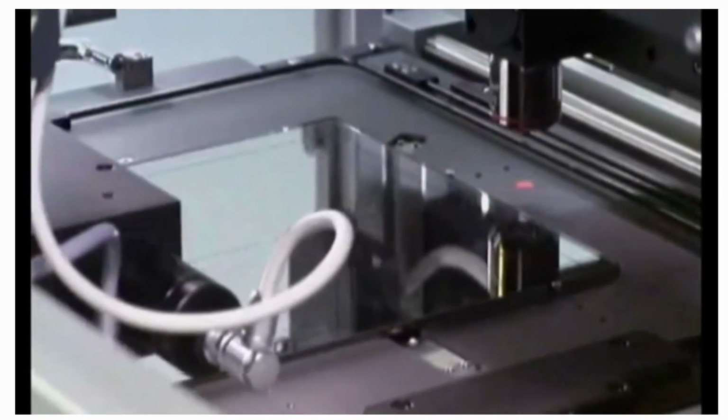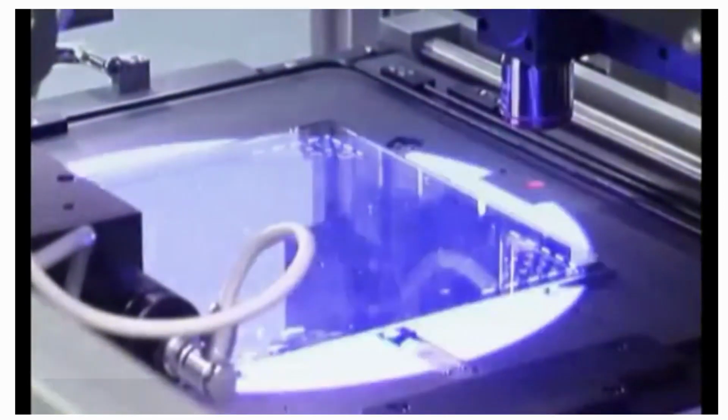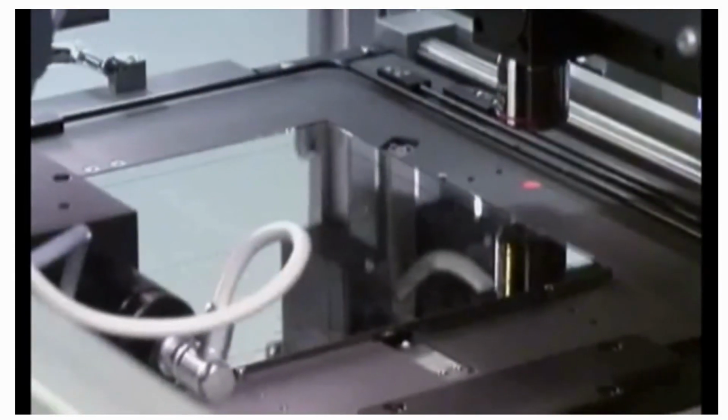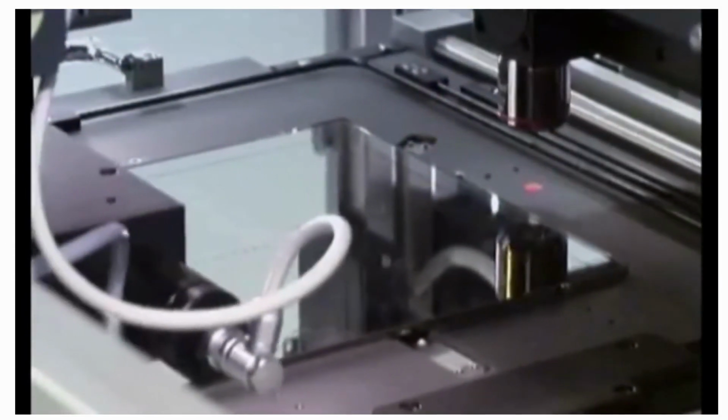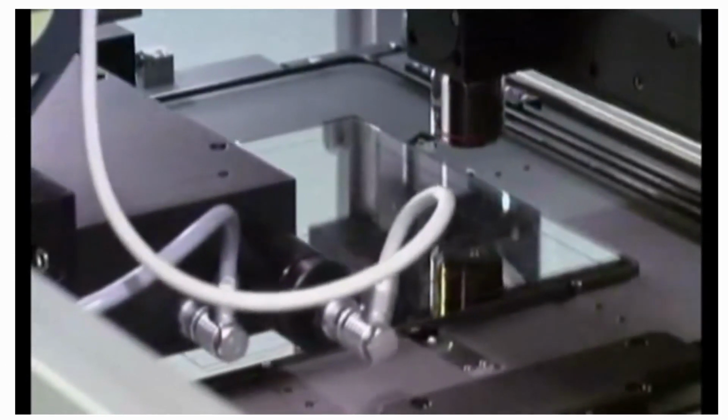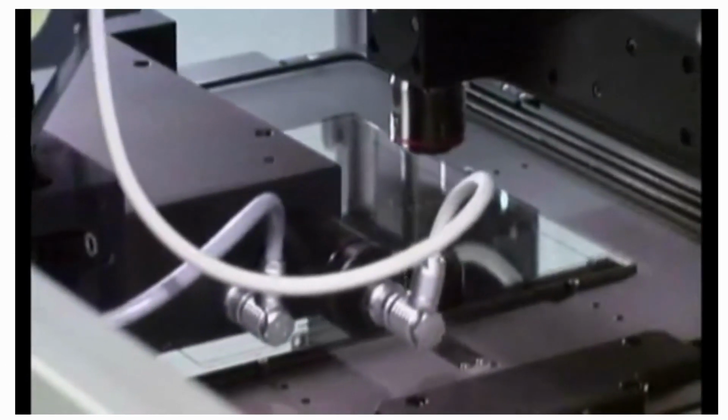The structures of the photomask are conveyed via shadowcast. The patented wafer leveling system from SUSS compensates for topographic variations and wedge errors, thus guaranteeing perfect alignment and exposure results. And the entire process is easy to monitor here on the touchscreen.